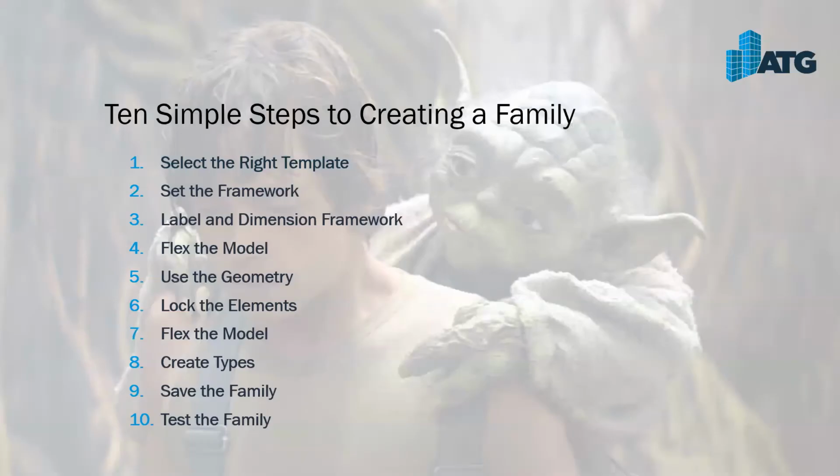So this is something that I showed in the previous webinar in my slide presentation. I would say it's probably the most important slide. It's something good to put by your desk as you're creating families. It's basically the steps that you want to take as you're developing the families. So in the last webinar, we selected a family template to start out with, created the framework, so that's developing reference planes, and then I added some dimensions and some labels, which are parameters within Revit.